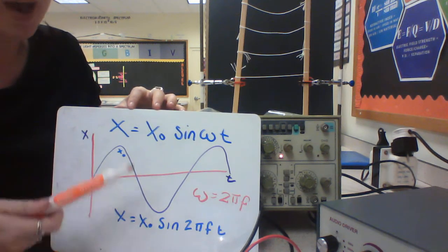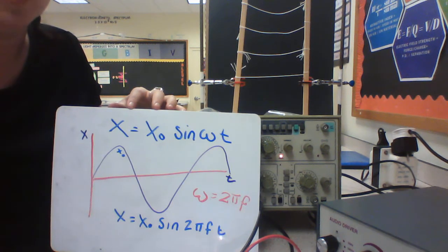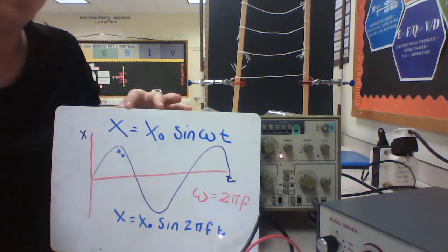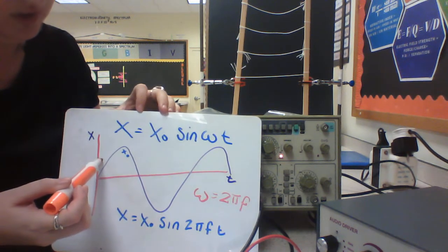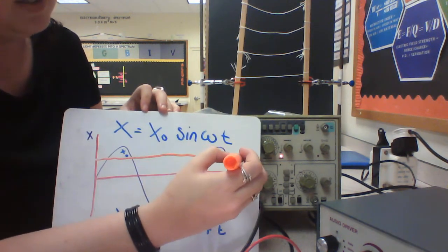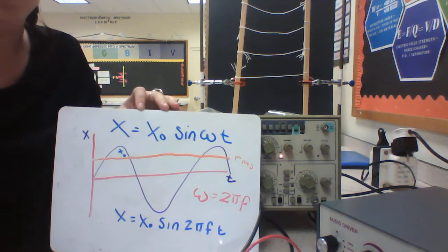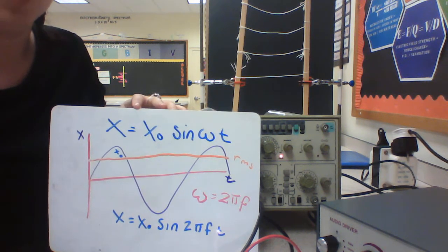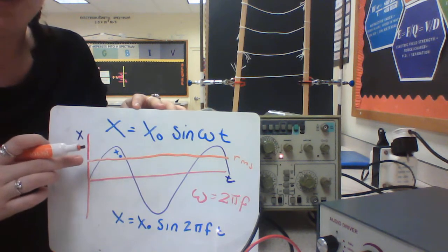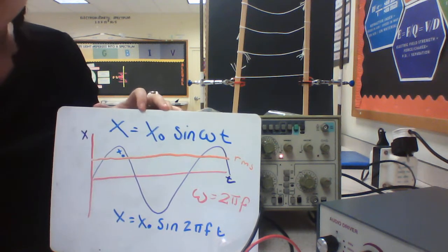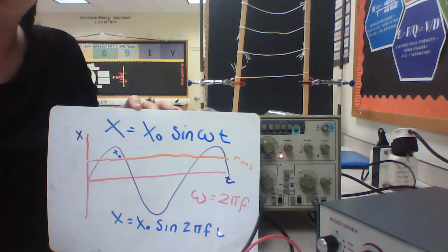So I can use the power equation, we're going to do this in lesson, P equals I squared R, that will make the I flip up, and I can find my average power, or my average current or voltage, I get a line here. This is known as my RMS. Your RMS current, your RMS voltage, is the same value as what a DC power supply would give you for the same power losses or the same thermal energy transfers. We'll go through the maths of that in lesson. But that's what I wanted to show you with this, and then we'll go through the PowerPoint in class.